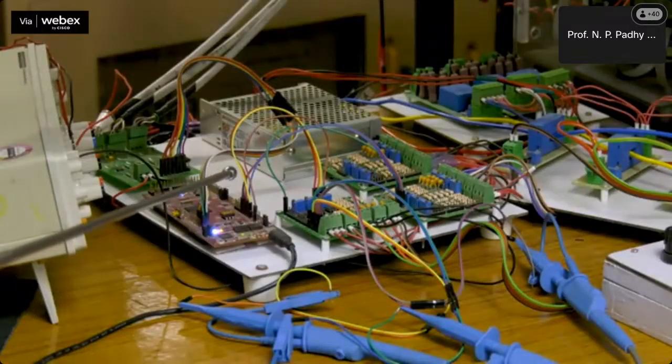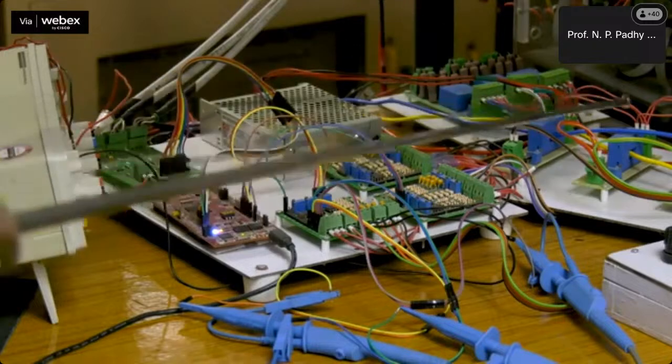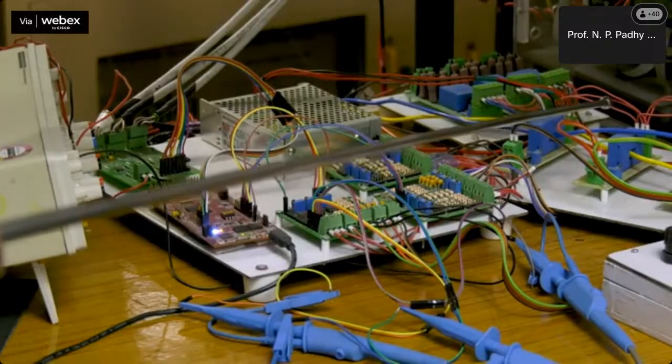Implementing a control system in DSP requires 3-phase voltage and current signals along with the DC bus voltage. The 3-phase voltage and currents are measured through sensors. The proportionate output of sensors is a sinusoidal signal, which is a bipolar signal. These bipolar signals cannot be given to the ADC pins of the DSP controller, because the ADC converts only the positive side of the signal into its digital form, and the negative side of the signal is always converted to 0. This causes a significant loss in signal.